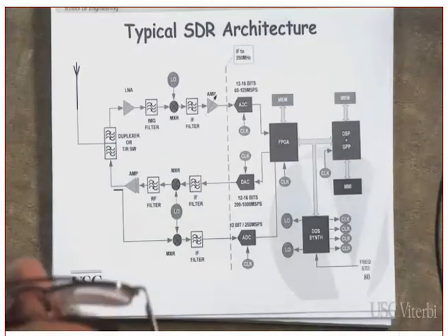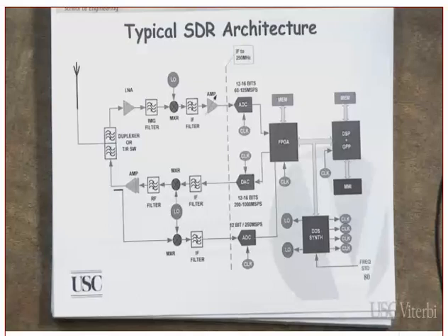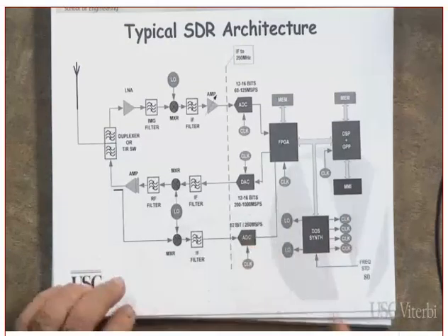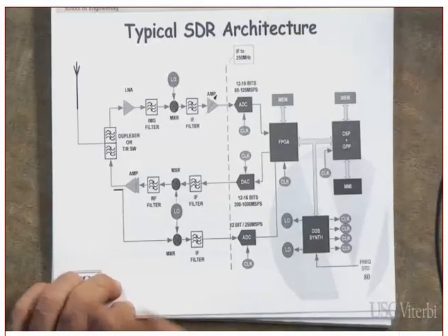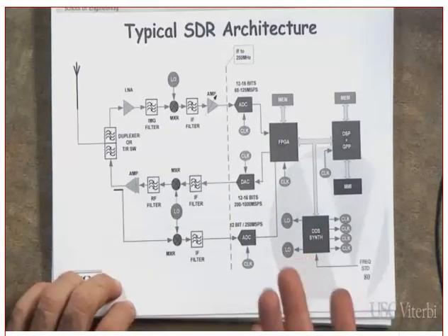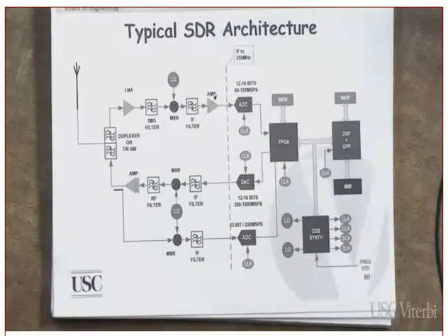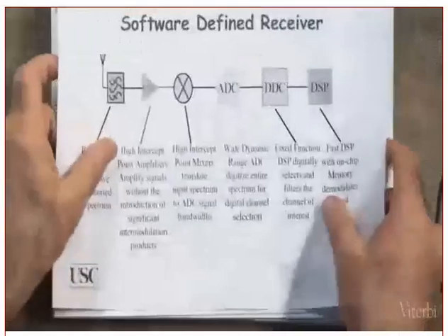Do you understand what a 15-bit ADC means? When we say, for example, 15-bit, it means the encoder represents every sample by 15 bits. Which means how many levels do you have? 2 to the power 15 output levels of the quantizer. The design becomes a little bit more complicated.